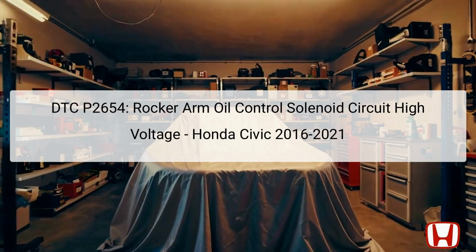Located near the cylinder head, this solenoid regulates variable valve timing, VVT, by controlling oil pressure. Elevated voltage may result in erratic VVT operation, leading to poor engine performance. This error code indicates a potential electrical issue within the solenoid circuit that needs to be diagnosed and addressed. Understanding this code and its implications is essential for achieving optimal engine performance in Honda Civics from 2016 to 2021.